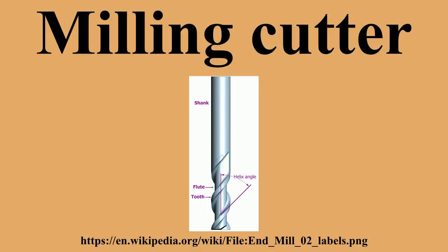Coating. Coatings, such as titanium nitride, also increase initial cost but reduce wear and increase tool life. TiAlN coating reduces sticking of aluminium to the tool, reducing and sometimes eliminating need for lubrication. Helix angle. High helix angles are typically best for soft metals, and low helix angles for harder, tough metals.